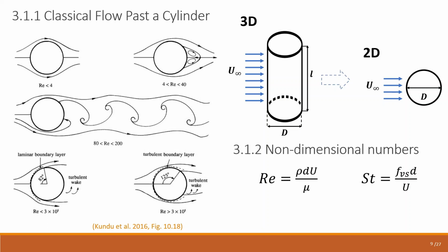Given the correct flow conditions are provided, there can be an asymmetric vortex shedding downstream of the mooring line. That is, when the flow goes past the mooring line, the viscous forces on the fluid tend to attach to the surface of the line. This creates a boundary layer. Upon further development of the boundary layer, the layers can begin to separate, which can then create a trailing vortice. These vortices are the source of the oscillating lift force mentioned earlier, which can lead to vortex-induced vibration of the mooring line.